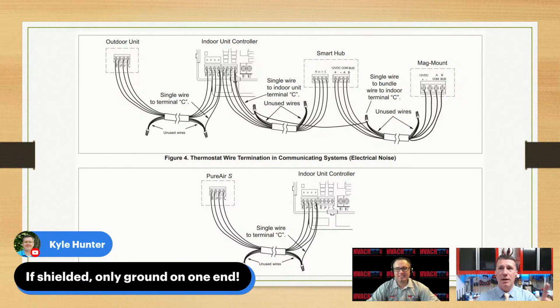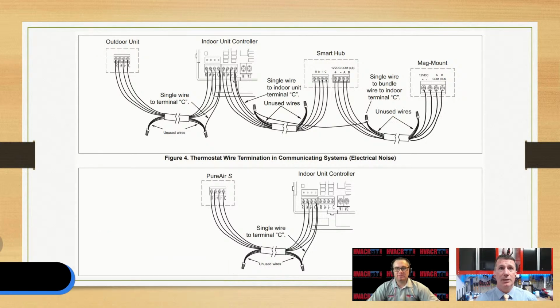What if I have a power supply at the outdoor unit, a power supply at the indoor unit, and a loop between them? This manual says no, we don't want you doing that. We want to make sure it's only connected at one location, the indoor unit. Okay, so the mystery is gone out of that.